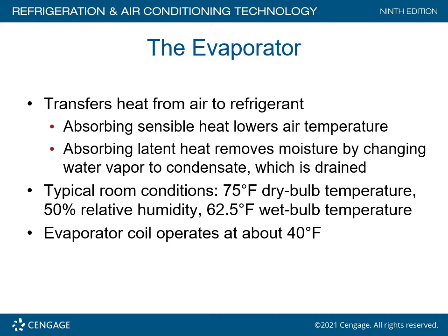I don't care what it is. I don't care if it's a mini split. I don't care if it's a split system. I don't care if it's a package. The magic number is that coil should be able to discharge 40 degree air out of that coil.